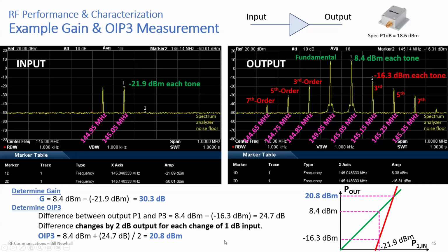So this becomes important when you're doing testing to look at the spectrum. Don't just assume, when you're working with RF signals, especially at the higher end of the power capability of a device, that the spectrum will be clean at the output. Here's a nice clean input, but at the output, you'll see intermodulation products at frequencies you may care about. You may not want those signals there.